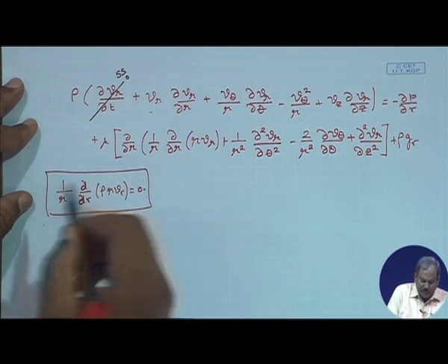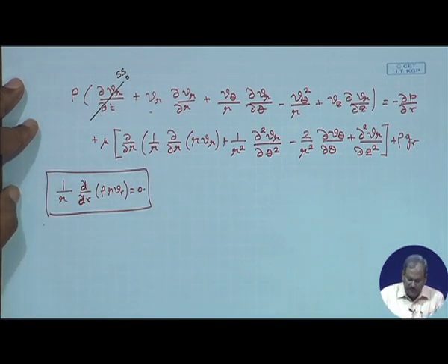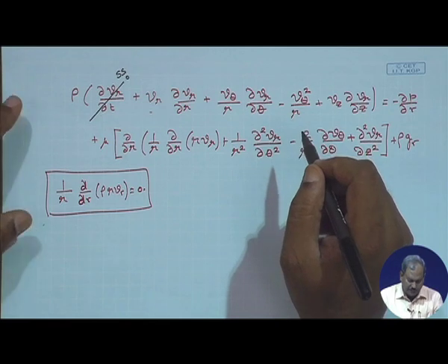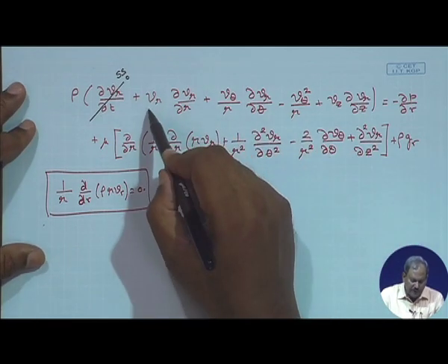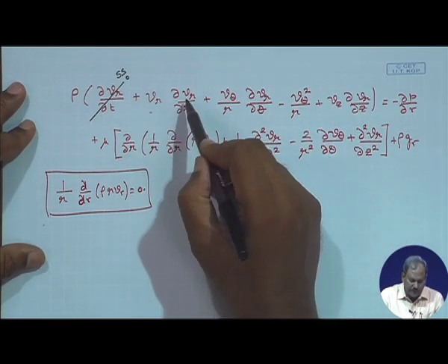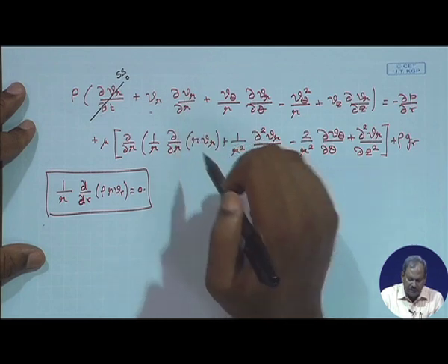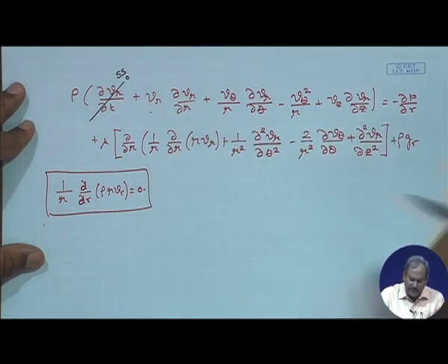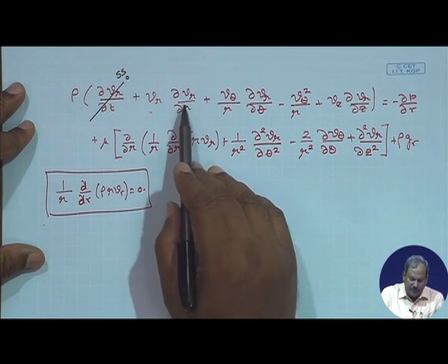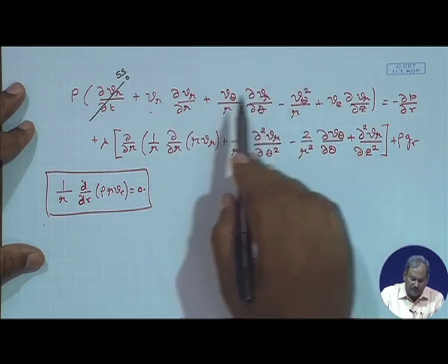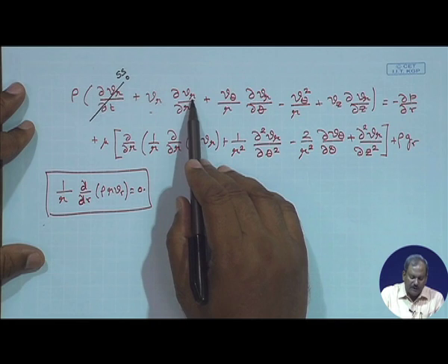This was the equation of continuity which we have seen in the past. Here Vr is not 0 and ∂Vr/∂r is also not 0. So as the liquid moves towards larger and larger values of r, Vr has to reduce.